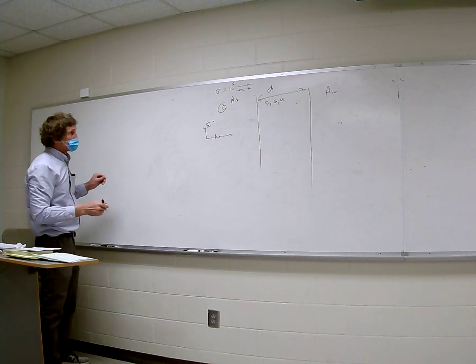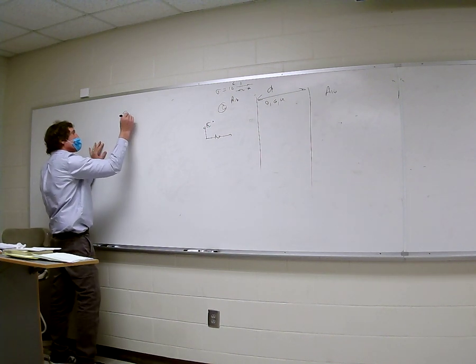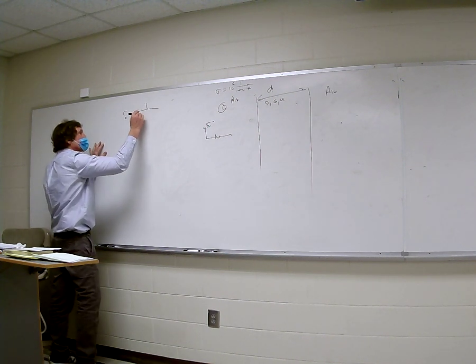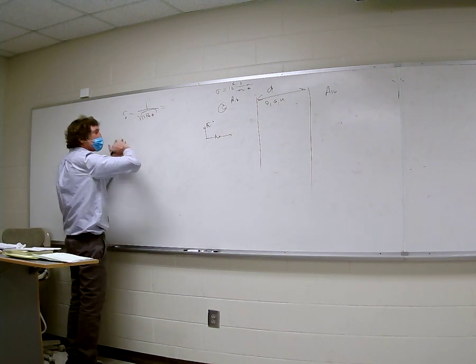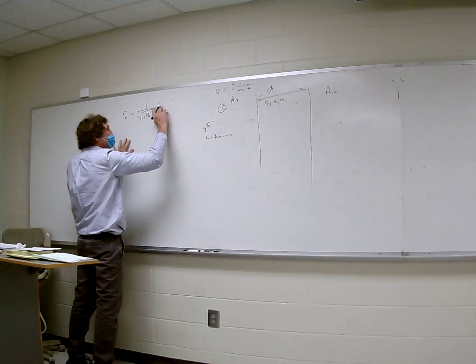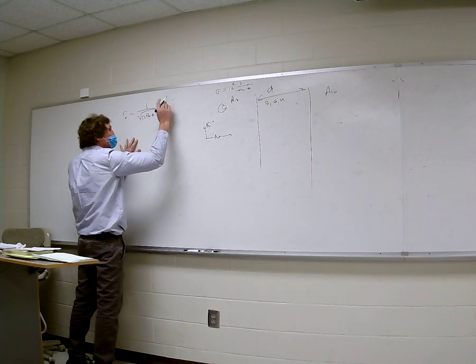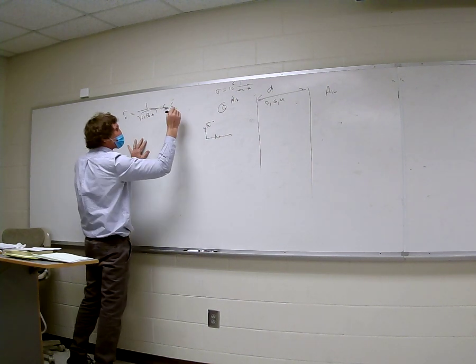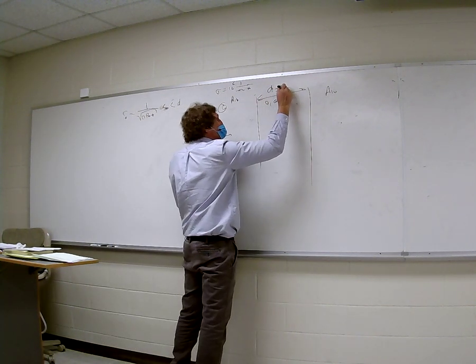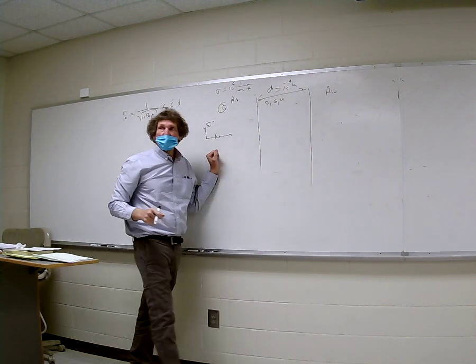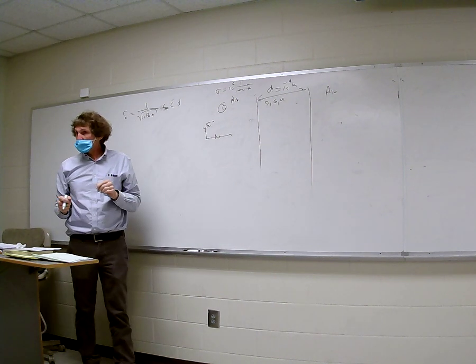Then you can figure out the skin depth is 1 over square root of pi f mu sigma, or 1 over alpha. And this is going to be, I don't know what it is, but it's much, much less than the thickness D, which is 10 to the minus 4th meters, I believe. Correct, class? So it's a thick shield. You all agree with me?